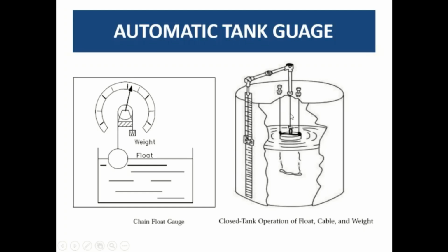If you do not periodically remove or clean your chain, ultimately this deposited material, which deposits due to the running down or entering of the material in your tank, will move towards this pulley, or maybe the second pulley, which may corrode your pulleys, or that may stick and jam the whole gauge's working.